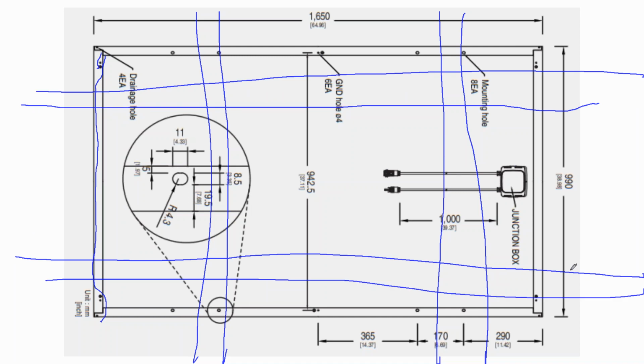And so that means the modules could go in portrait orientation or landscape orientation, and the racking could go in portrait orientation or landscape orientation. Many U.S. roofs have rafters going from the bottom of the roof up to the top of the roof, but on other roofing systems, such as tile rooftops or metal rooftops, you have support beams going east to west rather than north to south, and that'll impact whether your racking goes east to west versus north to south. Some designers will just say the modules are going to be whatever orientation best fits the racking. But architects may step in and say, no, we're going to go with landscape modules because it looks better on this rooftop than portrait modules.